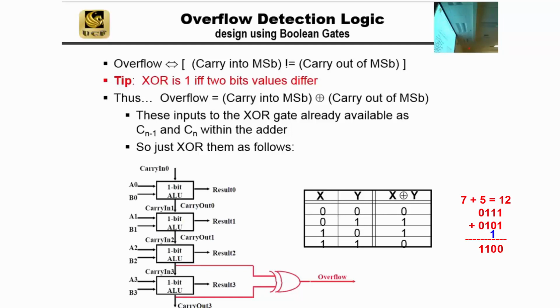It's not -4. So what went wrong? We overflowed. It's a condition. Overflow occurred. This means that this number is not valid. It means that the hardware we have cannot use this representation of 2's complement, and we don't have a choice to change that, because all the data is loaded in memory and all the registers are loaded with 2's complement values, because that's what every computer uses. So now overflow occurred. We have to do something. We either tell the user to repeat this with a different set of hardware, or we say that there's an error: overflow occurs.